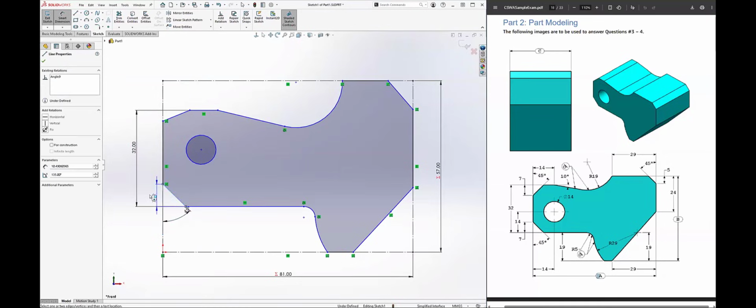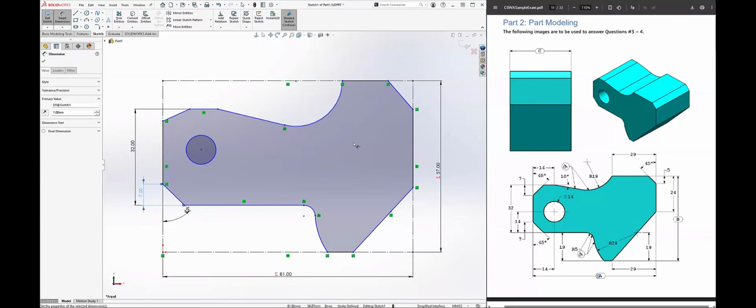I'm going to make this a height of 7. And another note for you, whenever you're working with a line that's on an angle that's not snapped to the horizontal or the vertical, technically it's a triangle. There's actually 3 different angles you can snap to. There's the hypotenuse, which is the width of the line, and then there's the vertical height and then the horizontal length. So make sure that you snap to the right one.